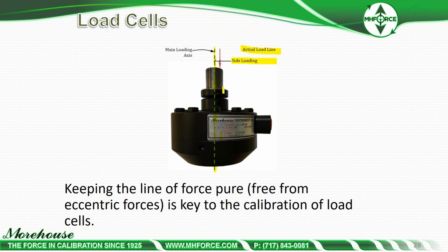If they have an integral adapter installed, they're much better than if they do not. This cell, the misalignment, if we did the same thing we did with that S-beam, the error source would be around 0.002 or 20 to 22 parts per million. It's dependent on the equipment. This one is not susceptible to misalignment errors, where the S-beam is very susceptible.